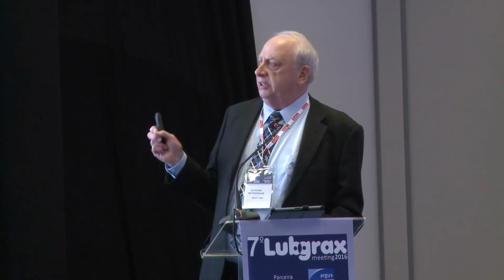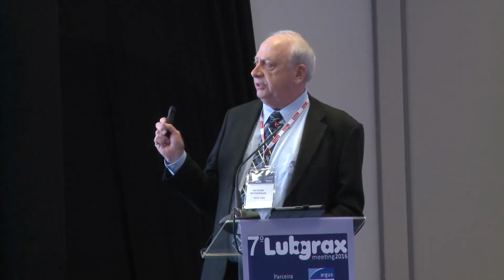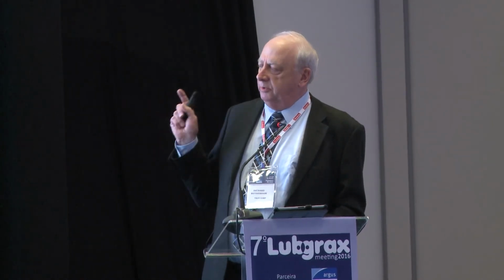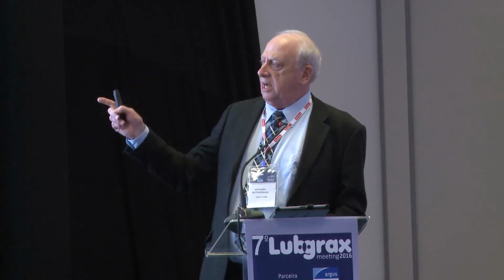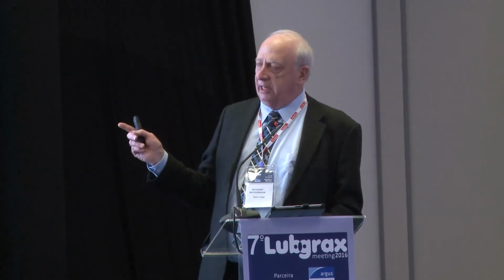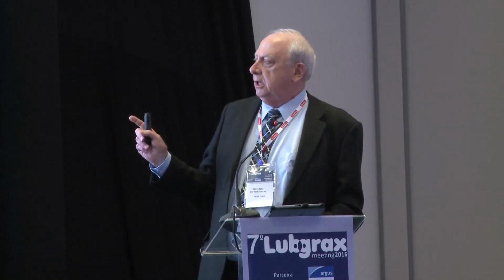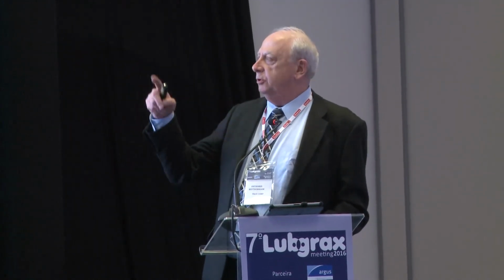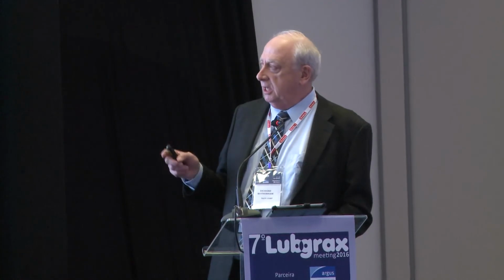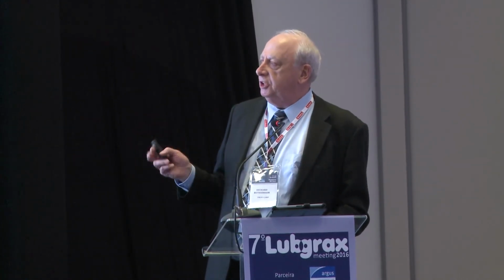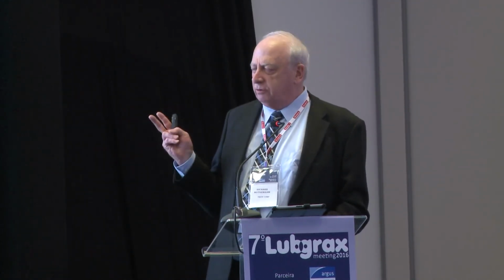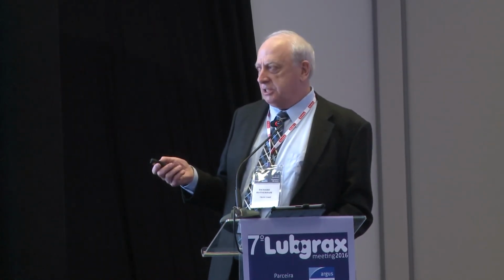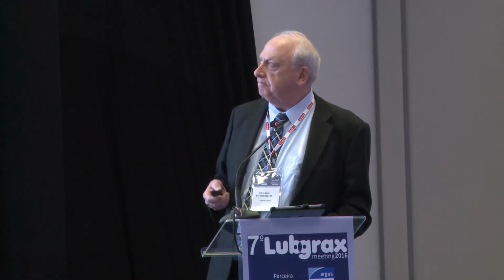One key point to note, because I talked about endotoxins and the health risks: of all the biocides listed, the only products that have been shown to neutralize endotoxins are triazines, oxazolidines, and glutaraldehyde, so the formaldehyde-based chemistries plus glutaraldehyde. So personally, I have a concern about removing the use of these things because I think there's a potential for exchanging one perceived risk, which the science doesn't support, with a greater risk that has been well demonstrated.